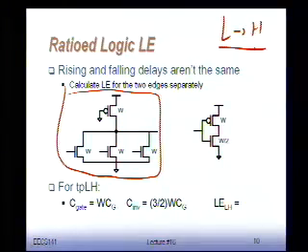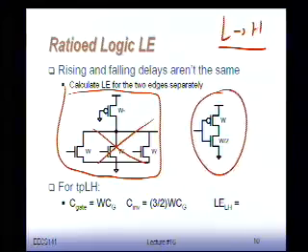Okay, in that case, this whole network is off. It's the PMOS pulling up. Now remember logical effort, we're looking at the input capacitance for the same driving force. So if you want a gate, a CMOS inverter has the same driving force, and since you're using W here, we have to compare with an inverter which has W in the PMOS and W/2 in the NMOS network. So the input capacitance of this thing is going to be 3/2 W. Right? It's 3/2, as we always did. So the W drops out.